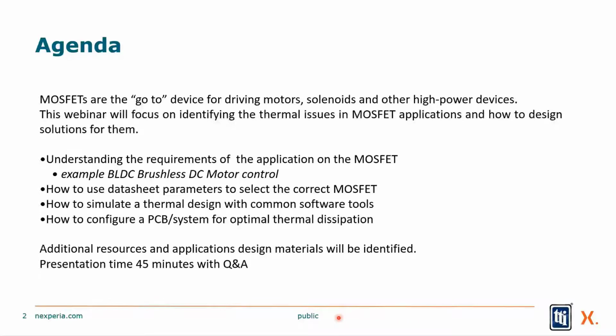Then this next section is relatively new. We want to show you how to simulate this thermal design with common software tools. And these are not the real exotic stuff that we can't afford a license for. These are tools that you can download for free and run yourselves and get a really good idea of how your system is going to perform before you buy the first MOSFET, before you put the first piece of solder on the board. So it's a really important tool for understanding if you picked the right part. You're going to simulate it.